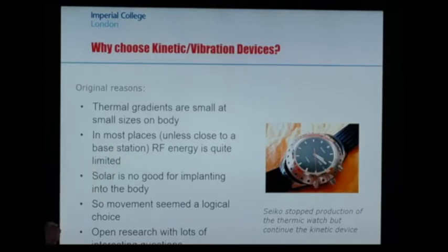If we talk about harvesting ambient radio frequency, that's also an extremely limited technology. If you want to actively beam power from one place to another, as you saw in my talk the other day, you can do that inductively and you can do it quite effectively. But it requires a dedicated source. You can do things in the far field. You can have a dedicated far field antenna and you can power something potentially at the other side of the room. But it requires a dedicated source.